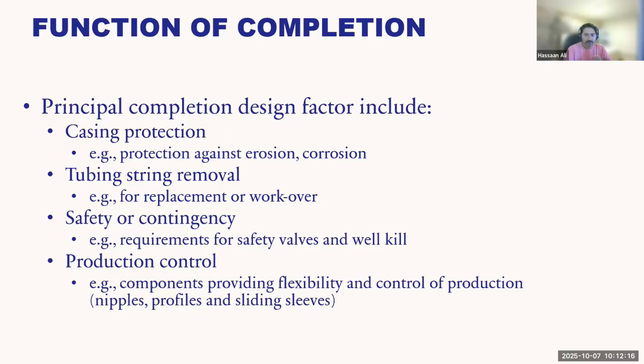You don't want to have very small diameter hardware because then it will constrain your production. It can actually hamper or damage the reservoir properties. So you want to have something which is optimized for that particular geometry.